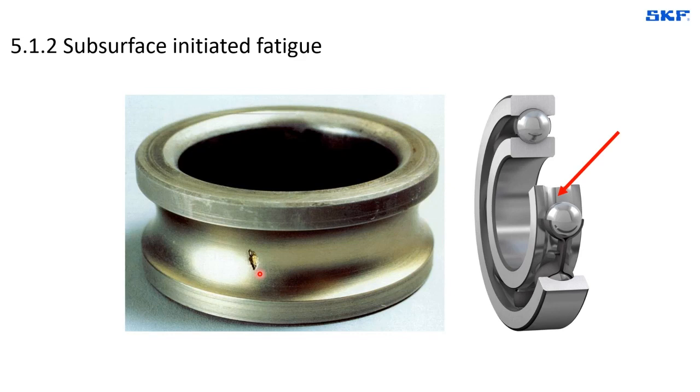The bearing is damaged, you can say, as the first indication of a failure happens. It can be flaking and spalling, and it can also be other things. But this does not mean that the bearing cannot continue to operate even with this small failure. What we need to understand is that the longer we allow the bearing to continue to operate, the harder it will be to identify what was the original reason.